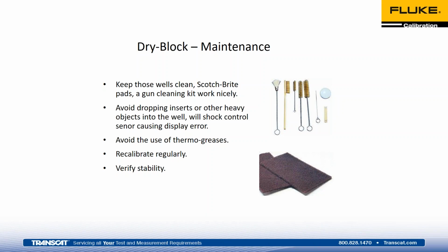As far as some maintenance, again, with the dry wells, the blocks are usually made out of some sort of metal, usually aluminum, bronze, brass. They do oxidize with time and use. What actually works really nicely is if you get a gun cleaning kit, you can clean the wells out really well. Another tip is to avoid dropping the inserts or heavy things into the well. This will shock your sensor.